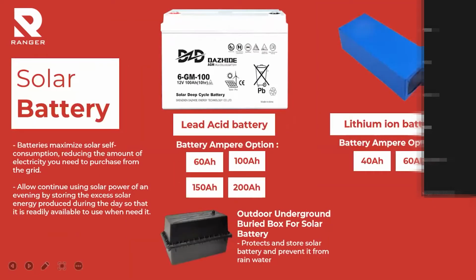Next, for solar battery, we have 2 types: lead acid battery and lithium ion battery. For lead acid, we have 4 options, which are 60 Ah, 100 Ah, 150 Ah, and 200 Ah. For lithium ion, we have 40 Ah and 60 Ah. The difference between these 2 types of battery is the efficiency. Lithium ion batteries are at least 95% efficient, and lead acid batteries are around 80 to 85%.